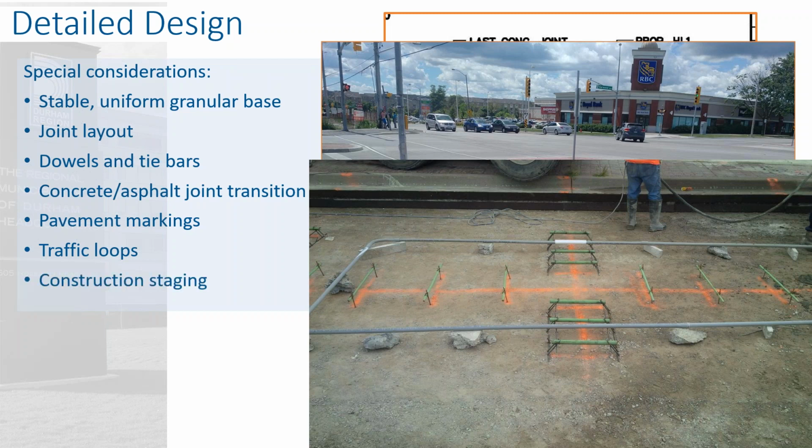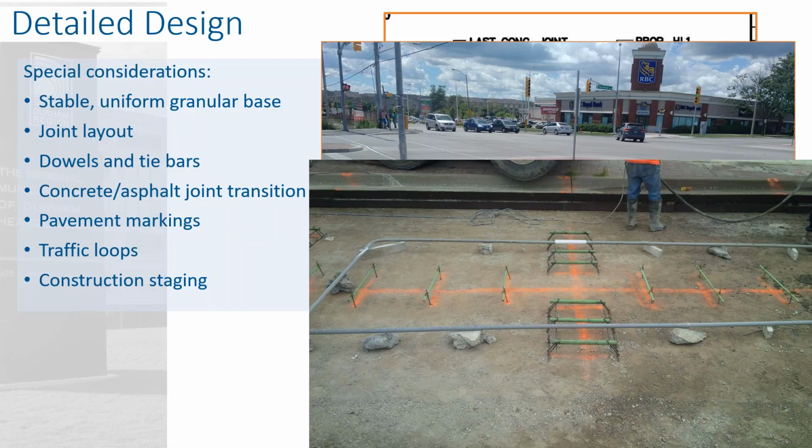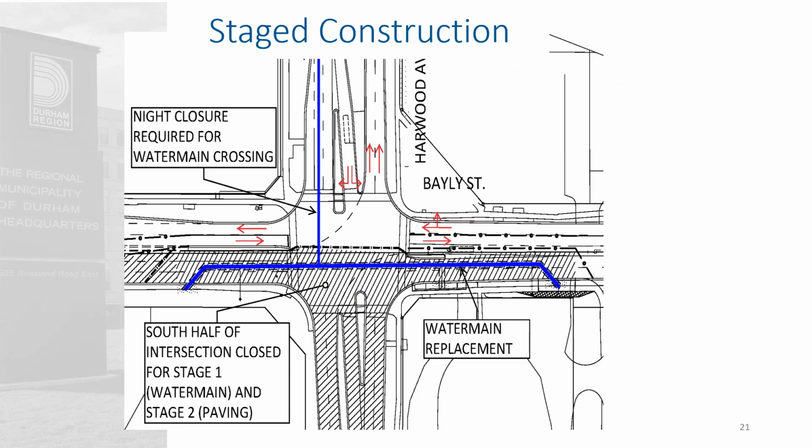Construction staging. The concern about concrete curing time. So we actually closed this intersection half of the time. And I'll show you a picture here. So we pushed traffic to the north and had one lane in each direction, and that south half of the intersection was closed. And then we were able to build